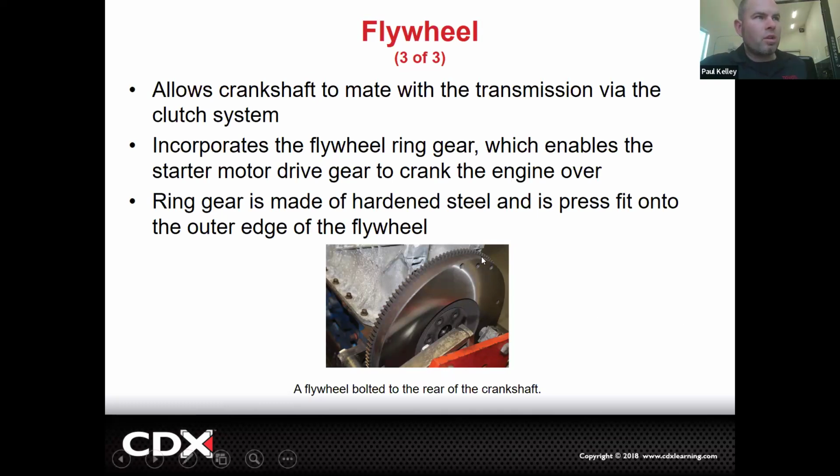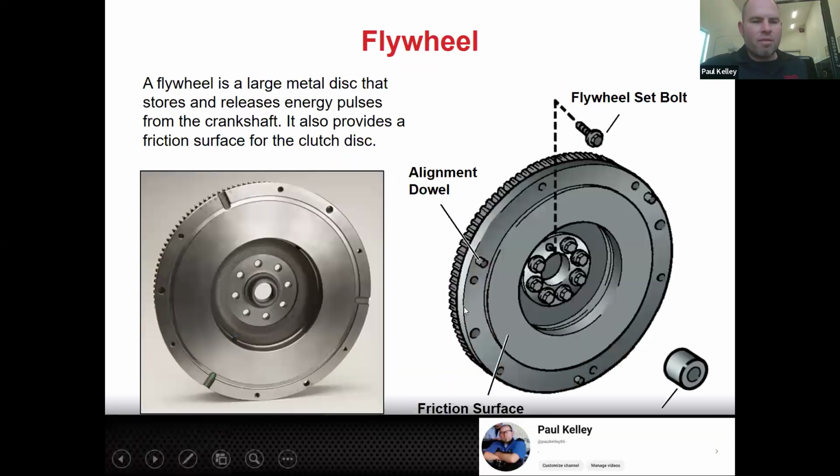This is a simple flywheel because it's flat. A lot of times we have them stepped. So this one, for example, you can just barely tell. This one is actually stepped. So this height is a little different than this height. Those are tougher to machine, and it brings in a whole new potential issue. If that one is machined wrong, you can get a clutch disc that won't disengage all the way, or you can get a clutch disc that will slip.